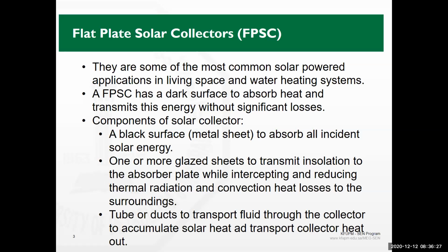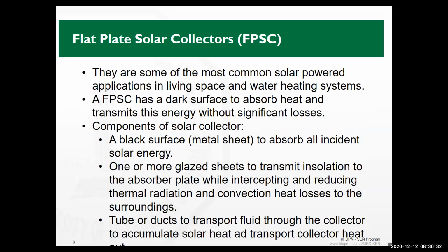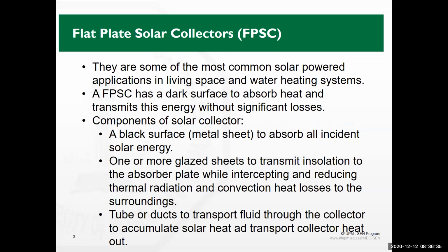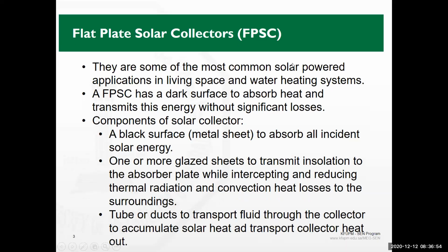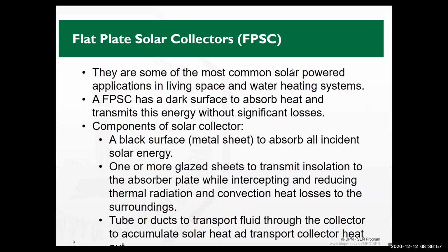Some of them, the name looks conventional to us because we have been seeing solar collectors in many places. However, a new technology came to the picture, where they make the solar collectors and apply vacuum in them. Using evacuated flat plate solar collectors is a rather new technology, and it is pretty efficient. It can have water heated to very high temperatures, and that's another interesting application for these collectors.